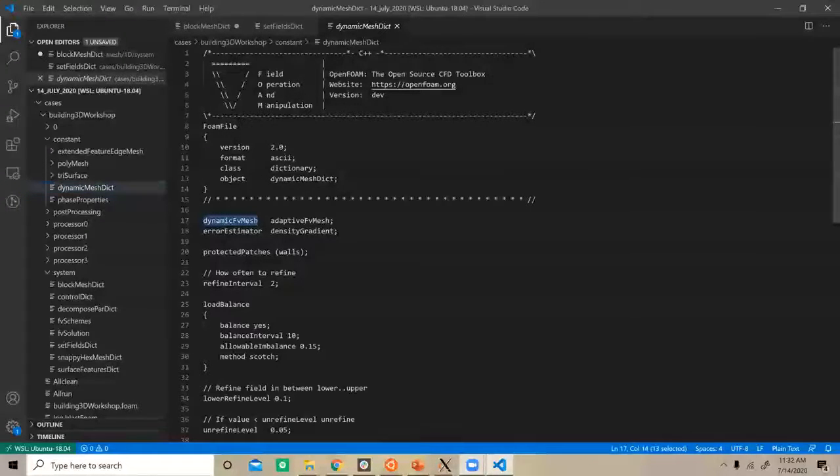And then we need to specify the dynamic mesh type. So we're going to be using the adaptive FE mesh. This is the blastFoam specific mesh type. So it uses things from the reference that Peter had mentioned earlier that has that adaptive mesh library. However, it's kind of been expanded and tweaked a little bit, really, for blast and compressible specific things.